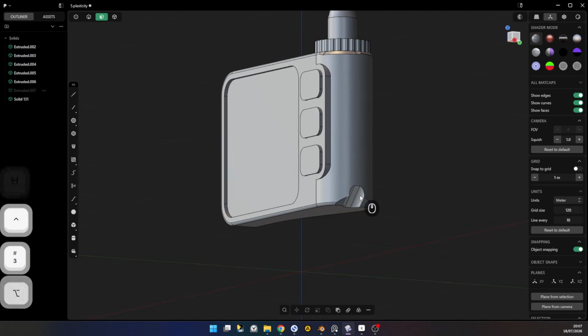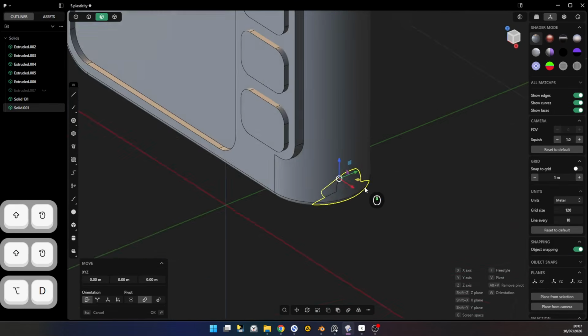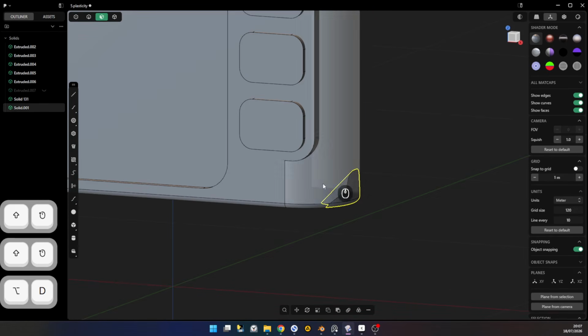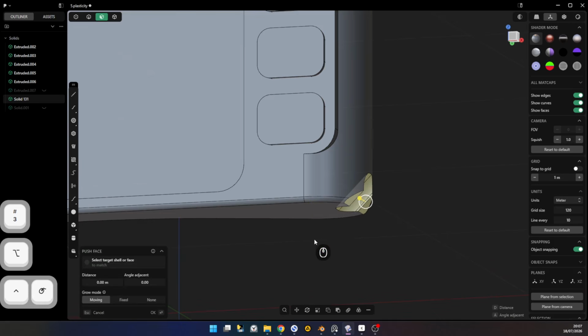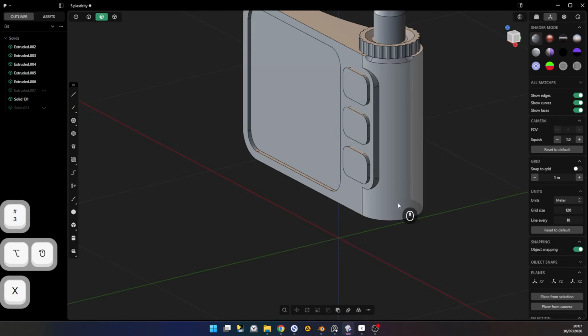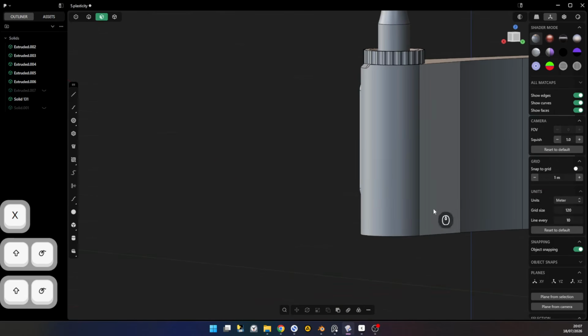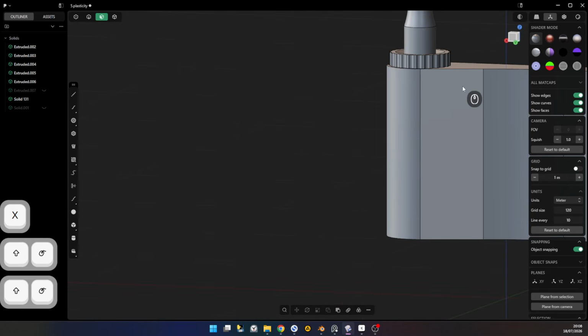We're gonna select those, that, gonna press Alt D to create a boolean shape for it that we're gonna use later to get that cutout back. We're gonna hide it as well. Now we're gonna delete that, and we're gonna delete that fillet. Okay. Now we need to somehow draw the shape that we want to cut out, that we want to be ergonomic.